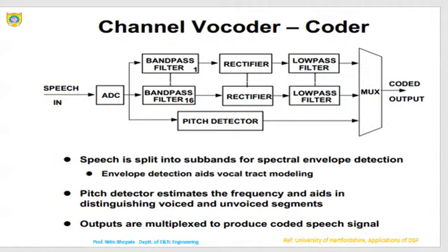A pitch detector tries to distinguish between the voiced and unvoiced segments. It is quite easy to identify voiced segments with clear periodicity and unvoiced segments which are non-periodic. However, it is very difficult to assess segments that fall between these two extremes. A number of voice detection algorithms have been developed, but none performs well in all applications.